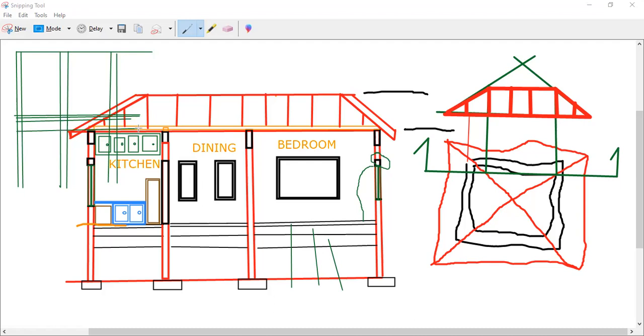From the top of the hardcore, we would then draw the next set of horizontal lines for our footing detail. The depth of foundation is normally taken from the top of the hardcore downward, so the ground level is normally in line with the hardcore. Here is our hardcore.